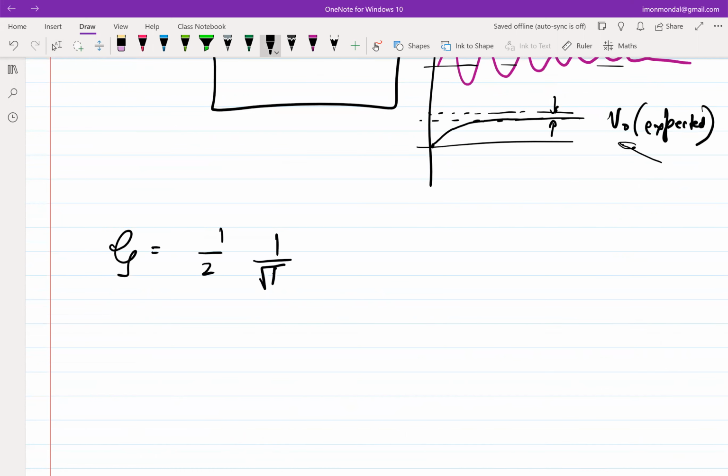So essentially it means that if the DC gain is high, you have to ensure that the second pole is even higher, farther away. That's the conclusion, assuming it's a second order all pole system. I haven't even considered zeros. It was a good question, since it seemed that having high DC gain is detrimental for stability. By stability, I mean it doesn't settle cleanly, it rings.